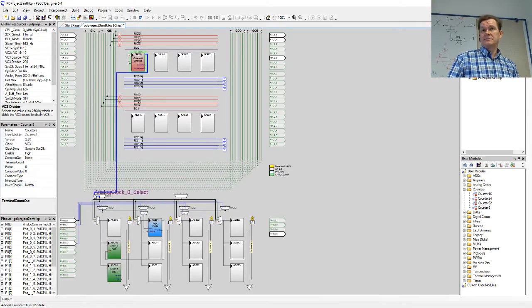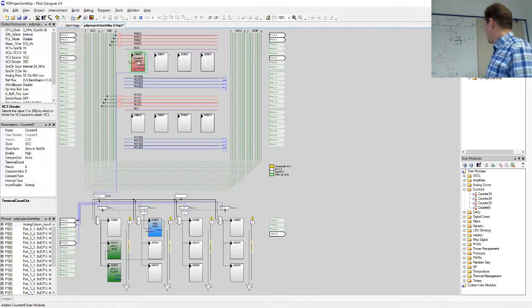Another modification. This now has a kind of bad divider, number 3. You don't really get a symmetrical clock rate using that. It would be better to have this one, for example, 6, and that one 10K. Then you can actually have the symmetrical clock coming out of that one.